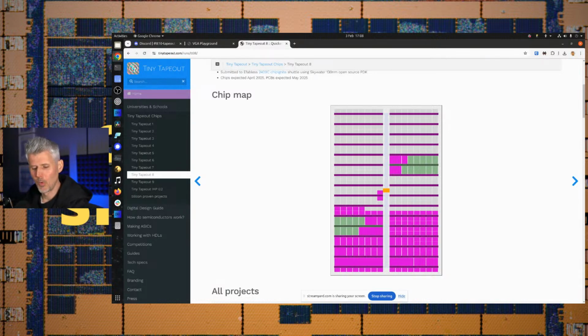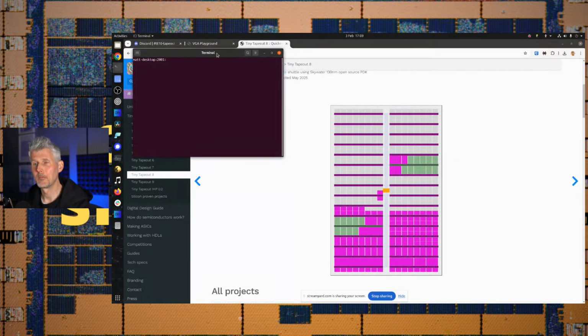So what we were thinking of doing was, instead of trying to control V-core, because as you drop V-core, that's going to also drop the voltage of all your multiplexers, if instead we have a digital design, but we put it in one of the analog blocks, then we can power the design through the analog supply, because we have a separate 3-volt analog supply. So to show you that, I'm going to load up the demo board.